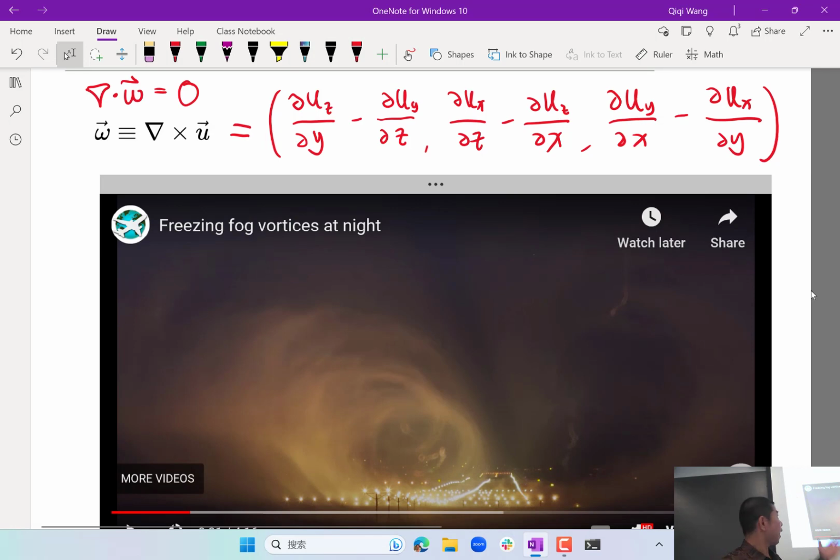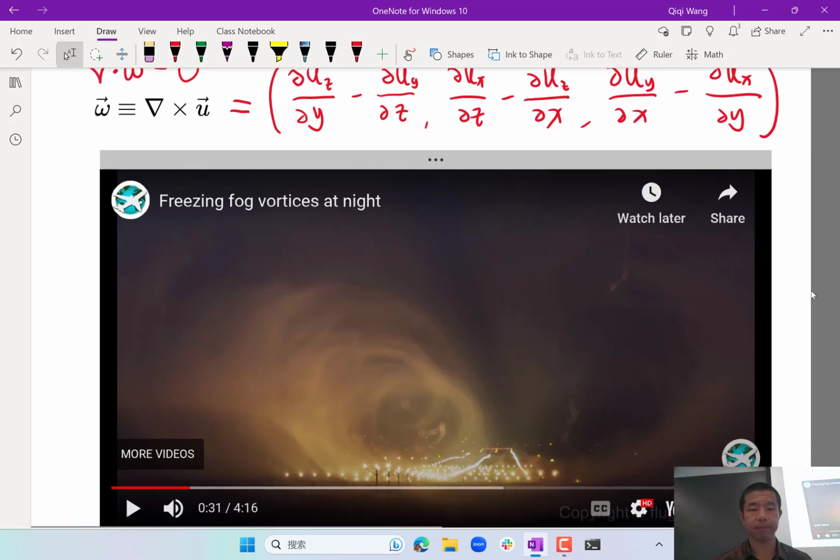One aspect is how the flow field behaves around concentrated vortices. And two is how vortices by themselves evolve. What is the dynamics of vortices in a flow field? If we can understand both of these components, then we understand most of the vortex-dominated flow fields, which is actually the case for flow fields behind lifting bodies.